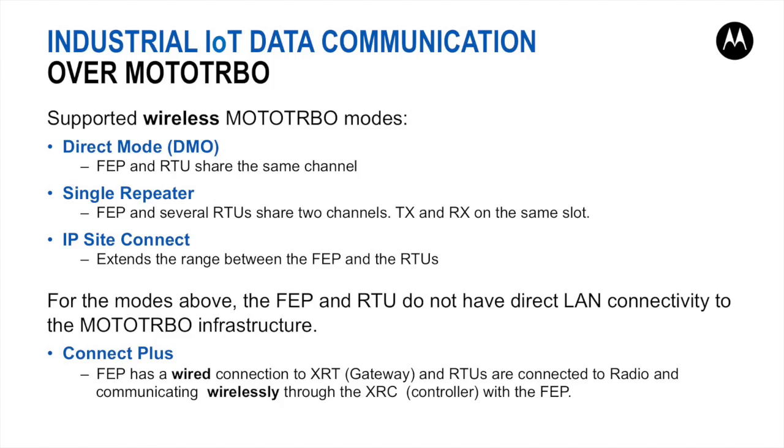Motorola ACE3600 and ACE4600 also support the analog mode of the MOTOTRBO radio, same as they did on the legacy radios, the CDM750, CM200, etc. In the digital mode, the MOTOTRBO radio is connected to the unit's USB port, and the connection is a USB host running IP over RNDIS. In this mode, the radio functions as a modem. The unit sends the radio requests, and the radio handles everything.